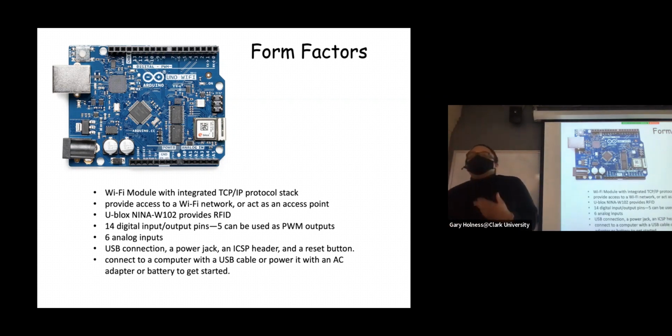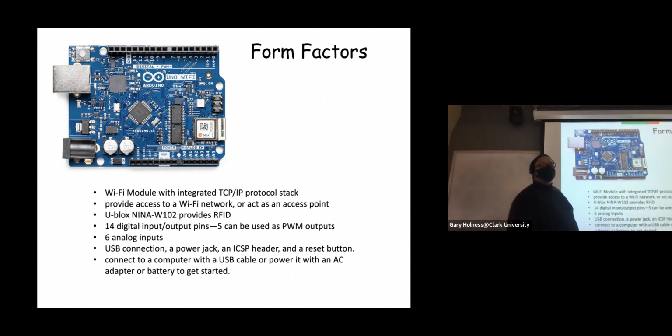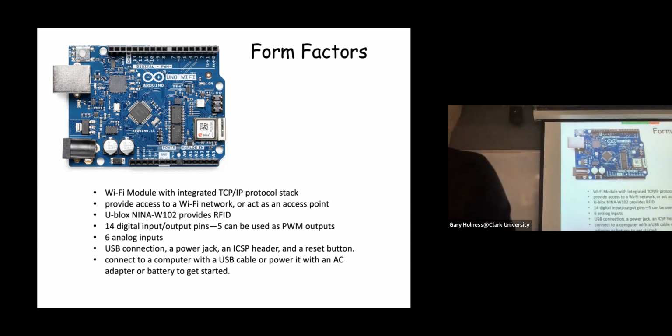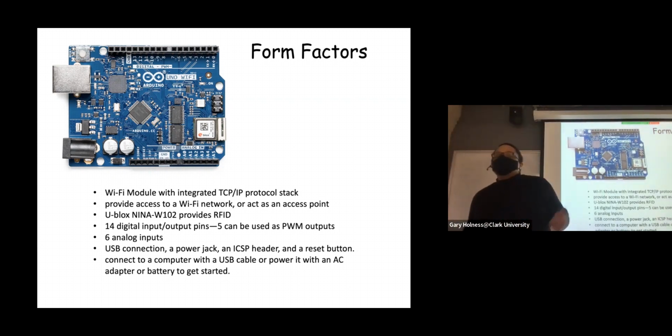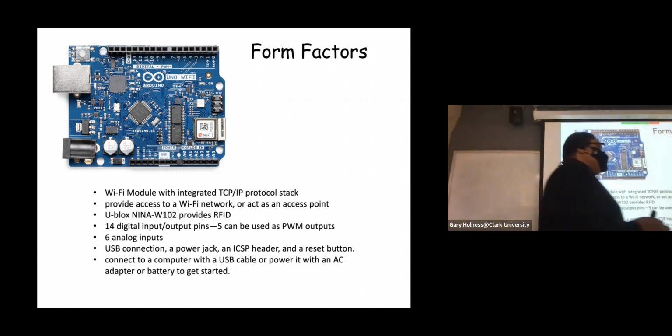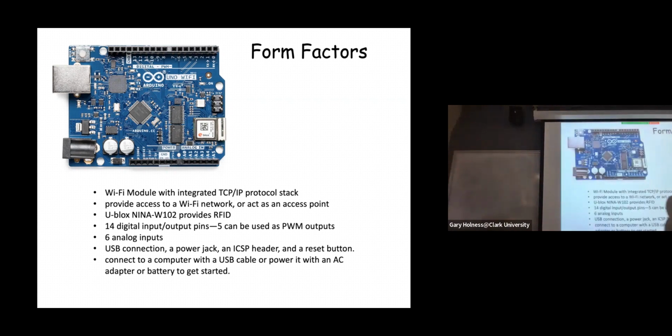Now, certainly, if you deploy such a thing, you have to give it a power source, and you give it its power source through the barrel power connector and not the USB. But you can still drive the board at the desktop power-wise from the USB connector, unless you're really pushing the board hard and your I/O devices, such as motors, are very power hungry. USB might not support the amount of voltage that your board is going to need. Okay? And any questions about this?